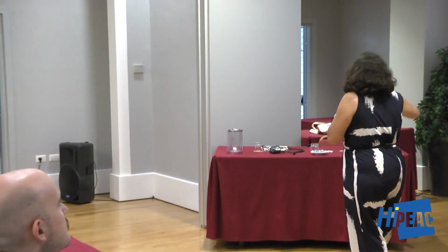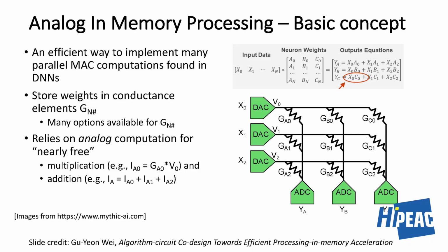With a very limited amount of operations that you do, and anything that creates a carry in some sense, you're out, right? No, I will show you how to do carry on this. It's coming up. You can do a lot more, but this is the basic idea: Kirchhoff's law and the dot product. What about accuracy? Is it as accurate as traditional? It is, yeah. If you can tune the ADCs properly, then you can get the right accuracy. But there's process variation, there are other problems, but you can get the right accuracy for a dot product with accurate ADCs and DACs. Yeah, good question.